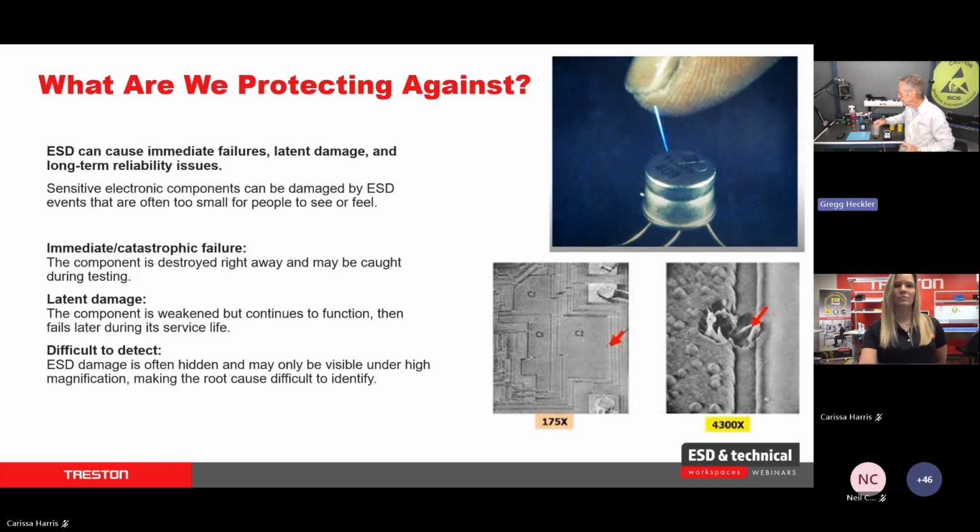Okay, Henry? That's right. And one other thing that's very important to remember is the amount of time, friction, and humidity all contribute to how large the charges will become. That's right. The lower the humidity, the bigger the charge, the greater the humidity, the lower the charge. So that's why in summertime, like right now, we don't get shocked a lot, because that humidity is keeping that potential off our body or keeping it lower. In the wintertime, especially in places like Minnesota, Arizona, etc., real dry, we're going to get shocked a lot, and hence we're going to have more of an ESD threat at those times of year.